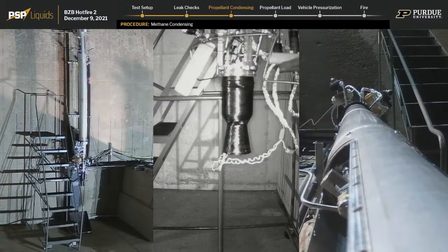This does limit the life of the engine, but it dramatically simplifies the design and allows the team to really iterate fast and get this rocket through the design cycle. And it also, in our case, allows it to be very light. It doesn't have to be made of metal. So what we have done for this project is directly overwrap the ablative material, the silica phenolic, with a carbon fiber overwrap. And then we integrate this TCA, thrust chamber assembly, up onto the injector.